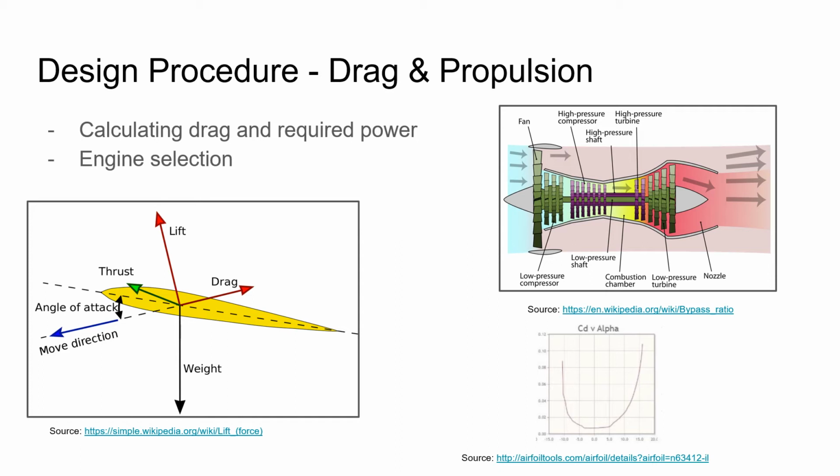This had to be calculated at two different positions, cruising altitude and takeoff. This was due to the fact that at those two positions, there's a different air density, different velocity, and a different angle of attack. The force of drag was used to find the power by multiplying it by the velocity of the plane. The power is based on the power needed to overcome the force of drag. Based on the power, we decided that a turbofan was the best option because the power was so big and needed a huge jetliner engine to power it.